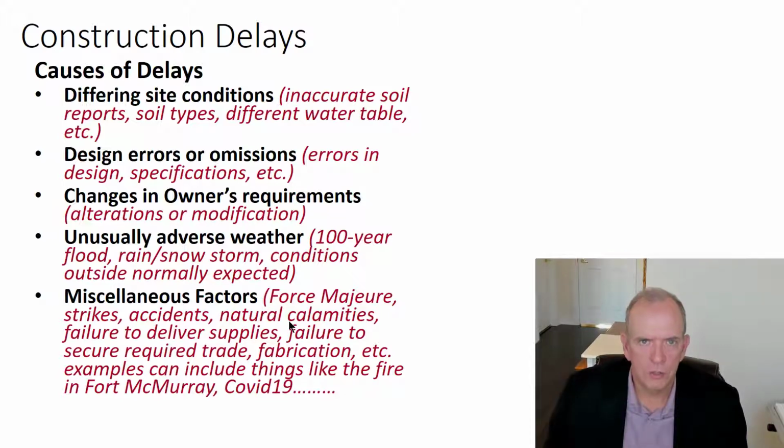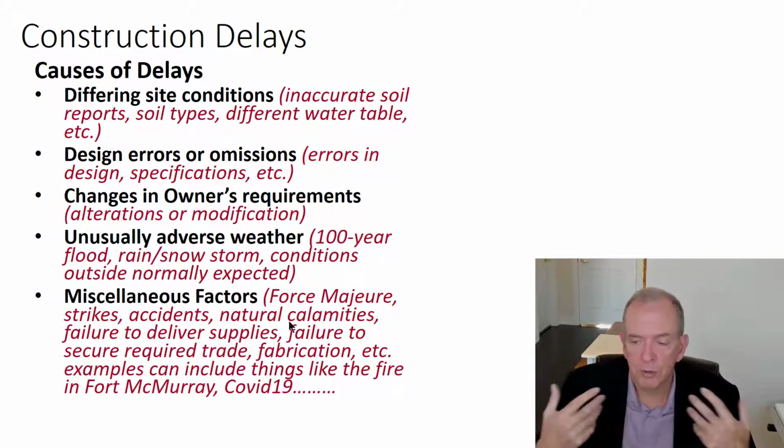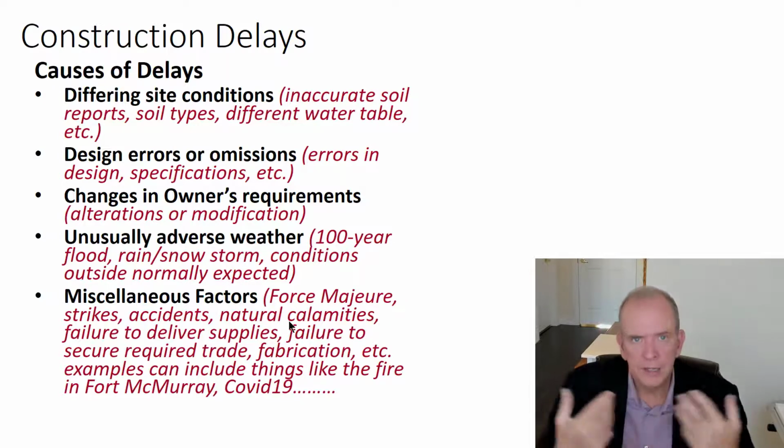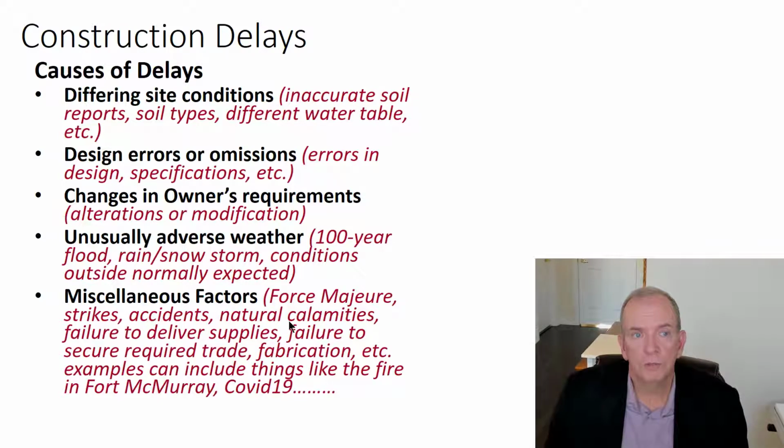They have what they call excusable non-compensable, and excusable and compensable. They have force majeure type delays that come out. They have non-excusable or inexcusable delays. That's where it's the contractor's fault. They delayed the project. Excusable, compensable would be the owner's consultant caused the delay in a design-bid-build project. Excusable non-compensable would typically be a force majeure event, some sort of extreme weather event or other factor.